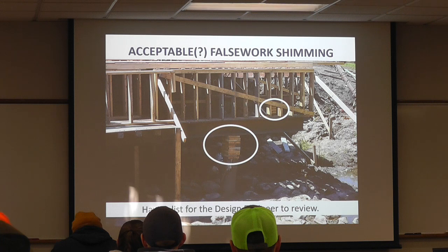This is, I keep this in here, probably the one and only. You win the prize for the most shims ever in a bridge construction project. But be looking for that, and this would be a perfect case for if the falsework designer comes out, he or she signs off, make sure you point out, okay, I've seen these areas, make sure you look at them. Are you okay with 15 2x4s stacked on top of each other as part of your falsework?